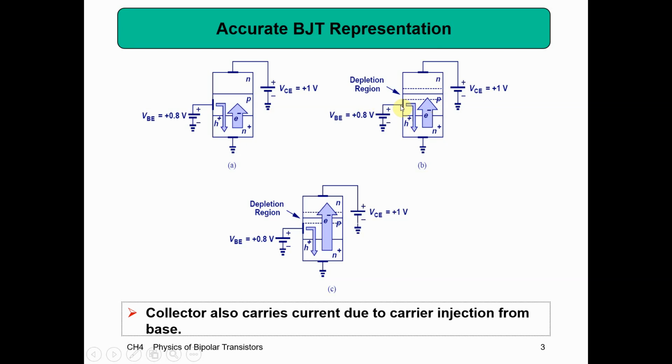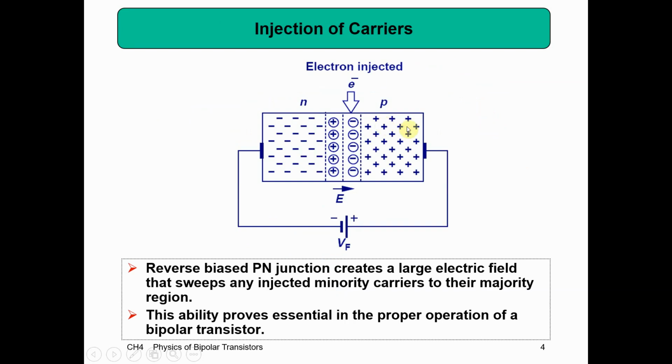And so the way this really looks is we have the base that is the control valve that controls the flow of current, or the flow of electrons up, which means that the current is flowing down. And that flow of current from the collector to the emitter is controlled by the base, by this injection of holes, which changes these two depletion regions.